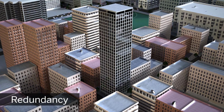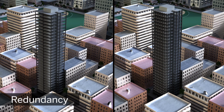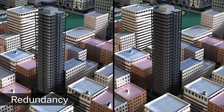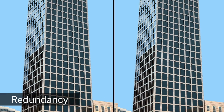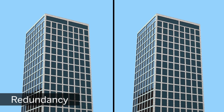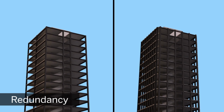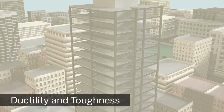If all of a structure's strength and resistance is concentrated in only one or a few elements, the structure will not have the necessary residual strength if these elements are seriously damaged, and it could collapse. If a structure is redundant, a relatively large number of elements participate in providing the structure strength, and if only a few are badly damaged, the remaining elements should have adequate residual strength to prevent collapse.